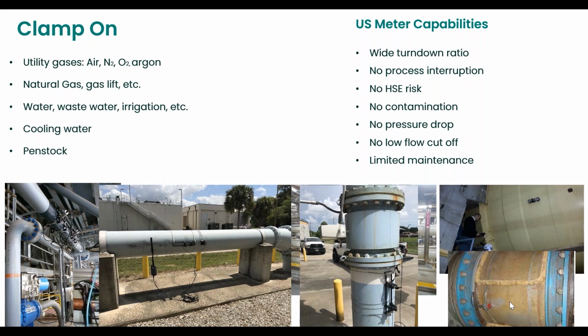And when I get into the PFA, because it's less dense, I will also have a kind of diminution of the velocity at which it travels, but I still need to know this one because it's a kind of dead time. So I don't want to be influenced by the time it takes for the sound to travel those thicknesses. So I need to enter the proper respective thicknesses of the two materials, so that I only focus on the time of the signal in the fluid I want to measure.